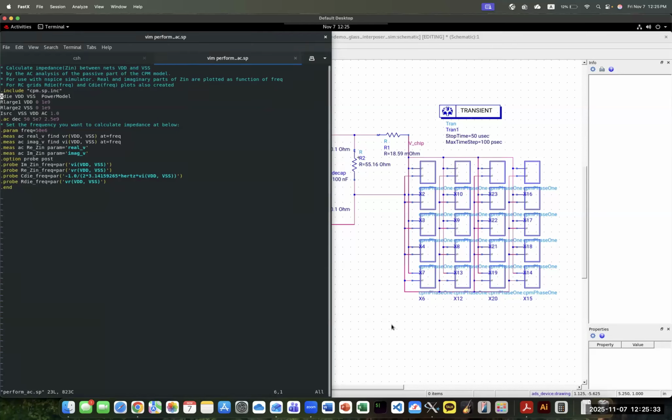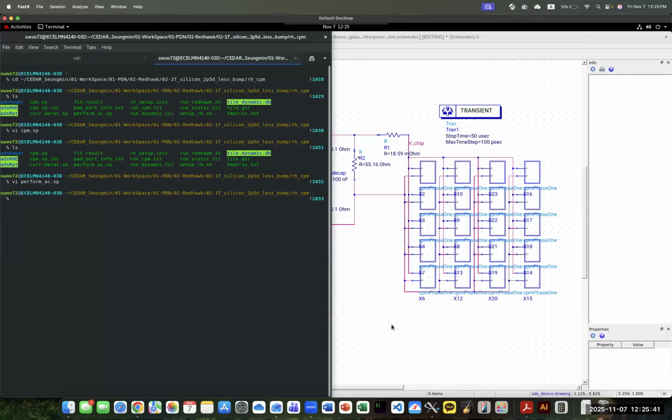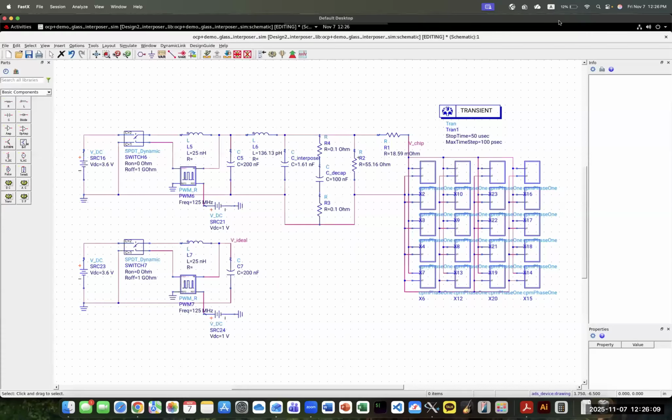The problem is if you run real patterns, you get very long simulation runs. Those kinds of tools running on a full netlist, you can't run milliseconds or seconds of simulation time. That's the problem. So that's where we are with this. We'll see where we take it.